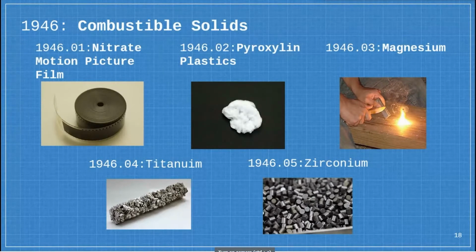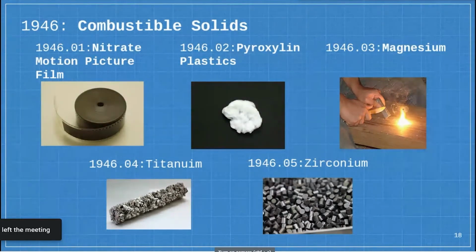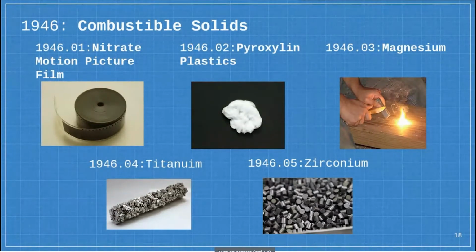So, paano mag-store ng mga ganito: cabinets in one workroom shall not contain more than 1,000 pounds or 454 kilogram of raw material. Each cabinet shall not contain more than 500 pounds or 227 kilogram. Each compartment shall not contain more than 250 pounds or 114 kilogram.